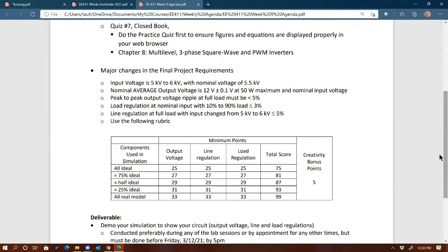So if you use low voltage, then you're going to have more current, and more current with long wires means more loss, right? So if you use low voltage, before the power gets to the sensors, the voltage already drops so much, right? If you don't use high power. So that's the reason behind this 5,000 volts to 6,000 volts supply, right, for these sensors.